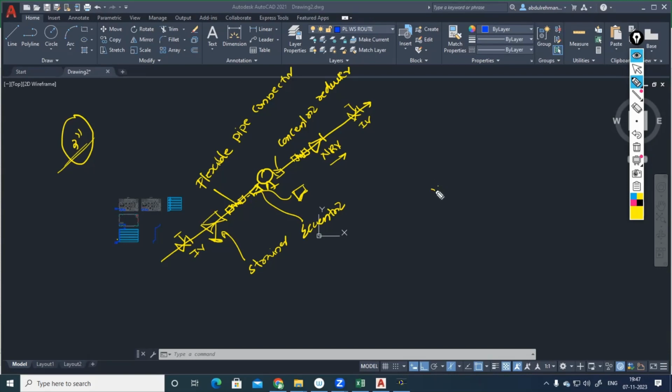There is an effect called the vortex effect. Due to the suction velocity, sometimes water will be rotating there. Once the vortex effect is created, air bubbles will be trapped inside, and that will affect the performance of the system. When the air bubbles burst, they will erode the pipe material and the pump material, correct?